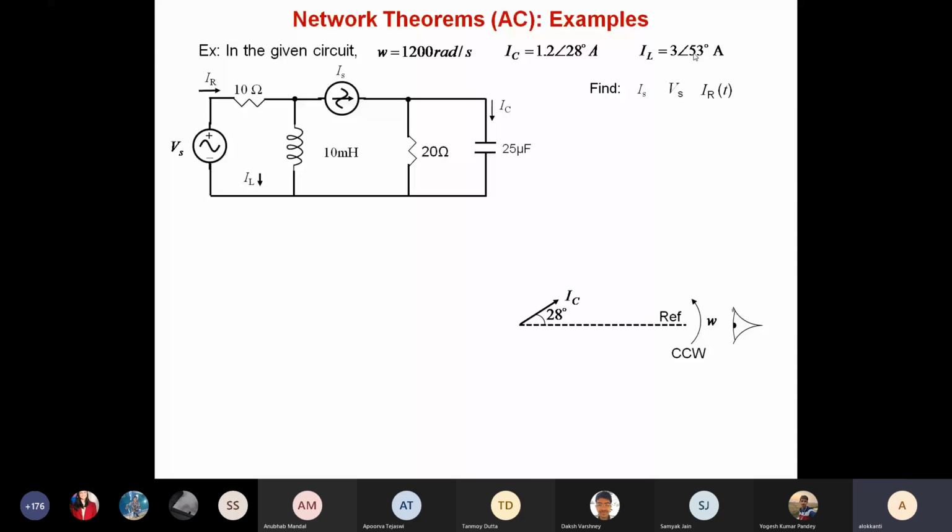You'll have to adopt that and draw the phasor diagram. Because suppose the voltage and current here are in the range of 1, 2, 3 and so on, and the voltages may be in the range of 40, 50, then using the same scale on that paper, you may not be able to hold it.